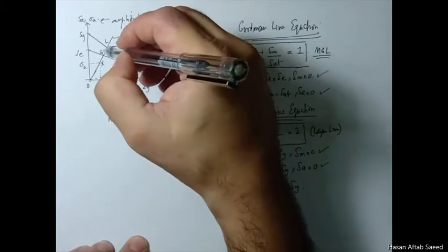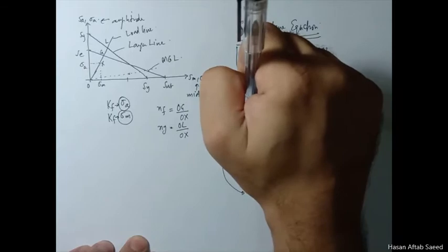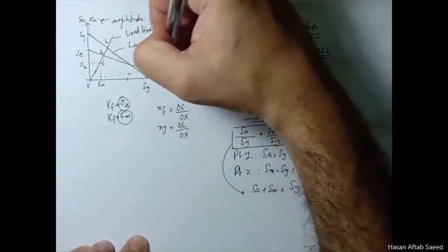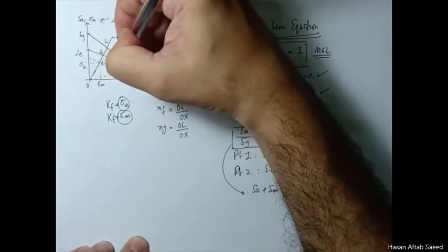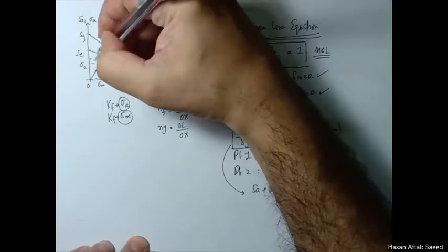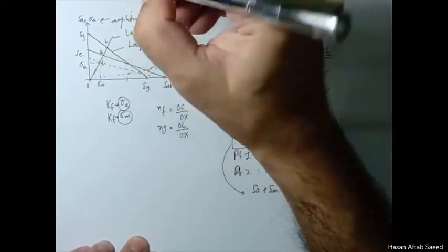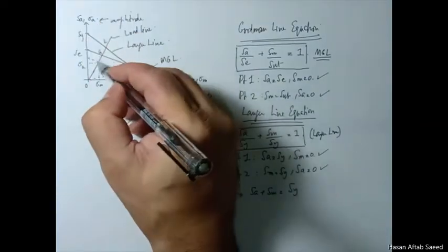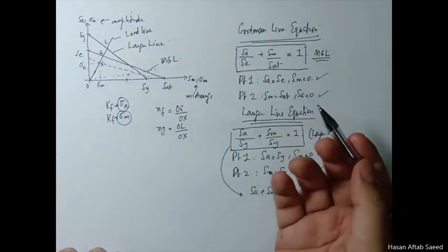So we need to be able to plot our sigma A and sigma M values in these equations. Essentially, if we have a factor of safety, for example n, and I'm just talking about this Goodman line now, this is the line which will run parallel to this Modified Goodman line if we keep a factor of safety of n between this point and this one. Because if this point lies on this line, then you have a factor of safety of 1.